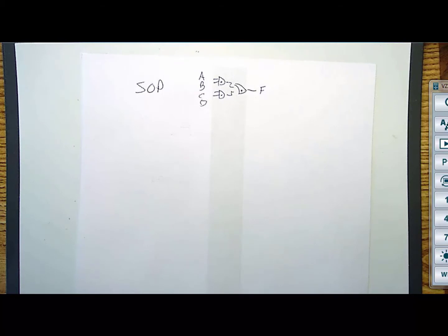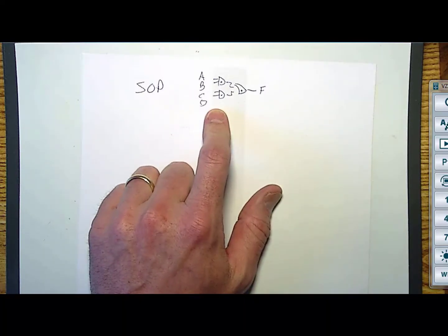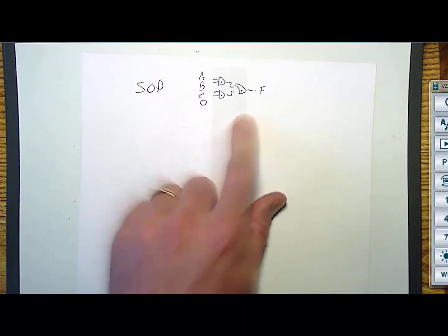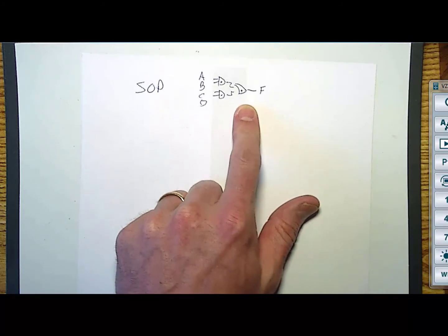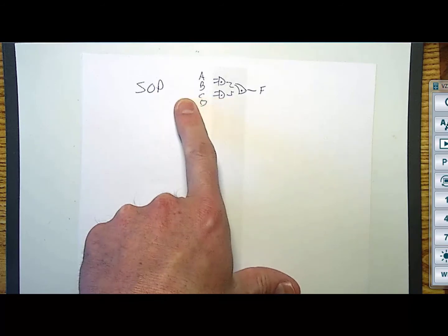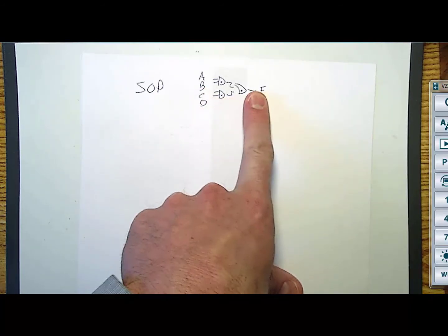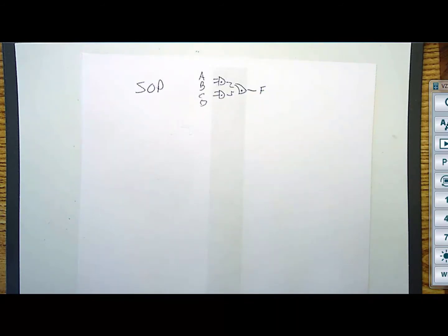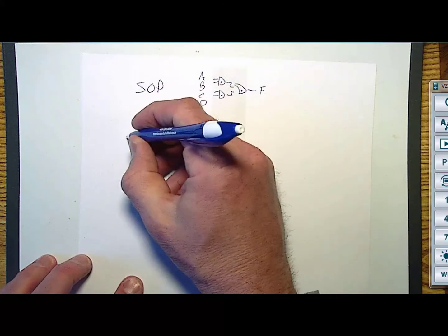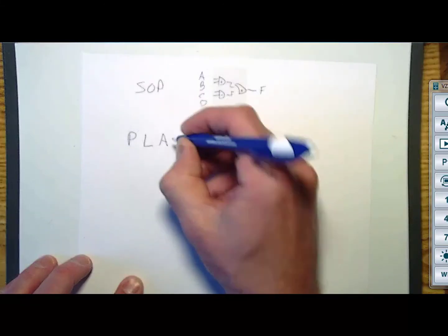If you don't know the final logic expression, but you do know that it's a sum of products, you can just go into a chip and throw down the AND gates, and you can throw down the OR gates too. All that's really left is programming which inputs are tied to the AND gates and which AND gates are tied to the OR gate. So that gets us to the historical aspect of the first programmable logic device, and it was called a Programmable Logic Array.